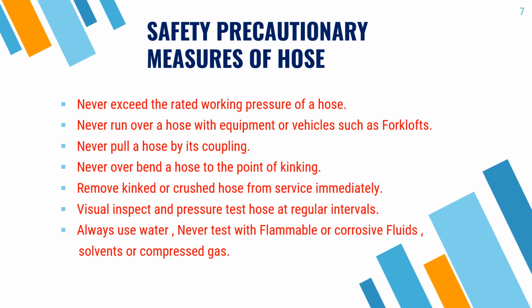Never pull a hose by its coupling. Never overbend a hose to the point of kinking. Remove kinked or crushed hose from service immediately. Visually inspect and pressure test hose at regular intervals.